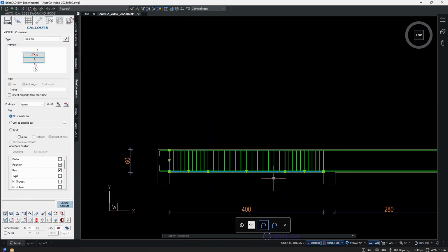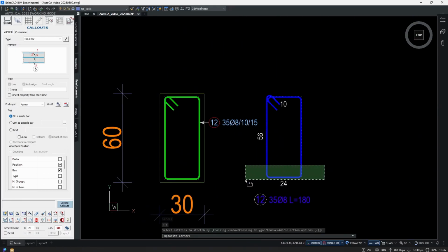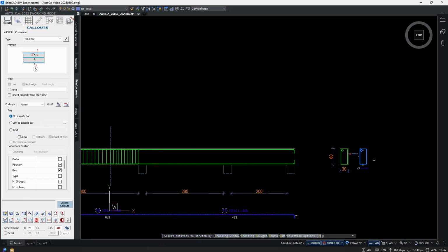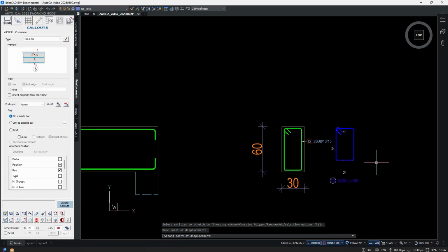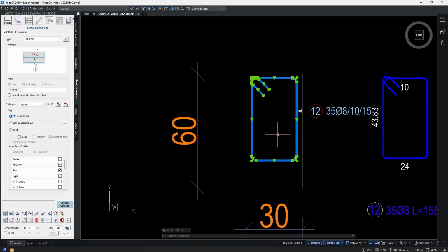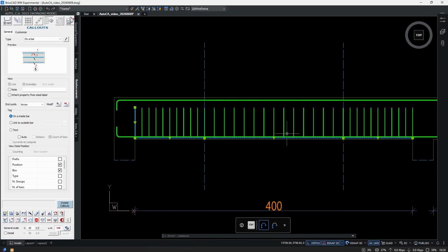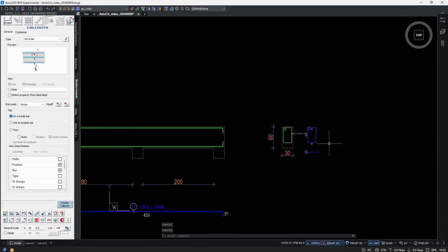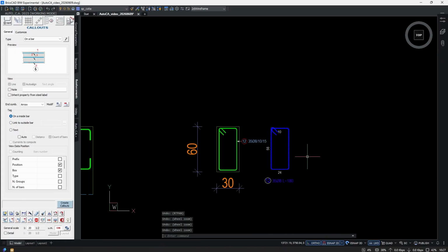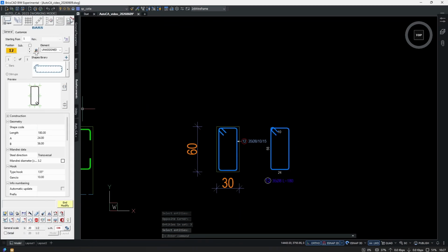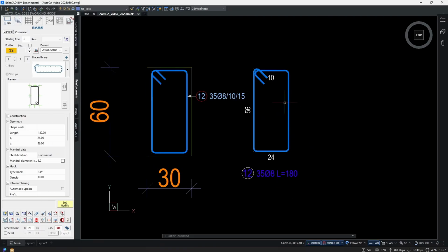You can check if you worked correctly with a simple stretch of the outside bar. Stretch it. The inside bar has changed as well as the distribution. So this means that the links are functioning correctly. Also, alternatively, if you want to check connections, you can enter into the modification panel of the outside stirrup and click on this enable/disable the zoom position of the bar option.